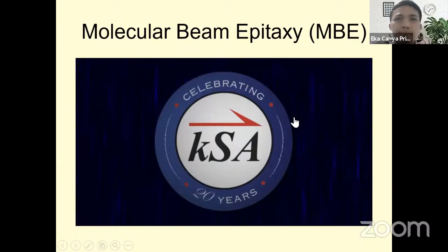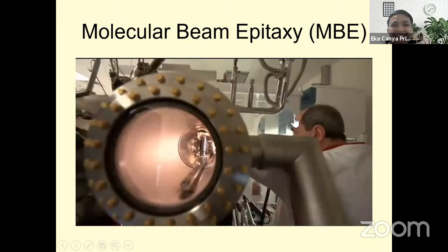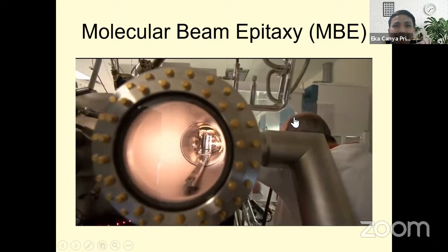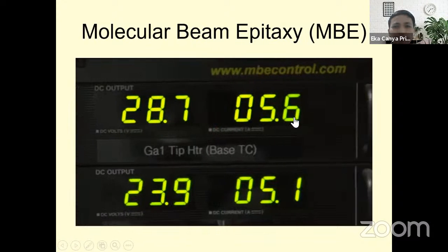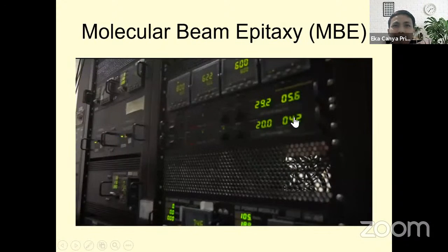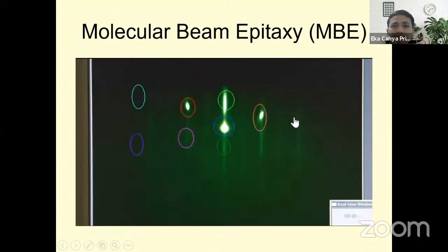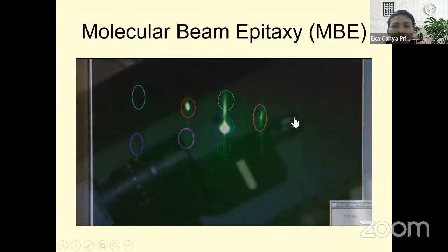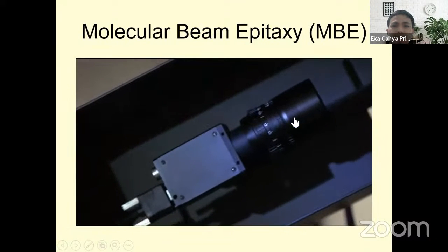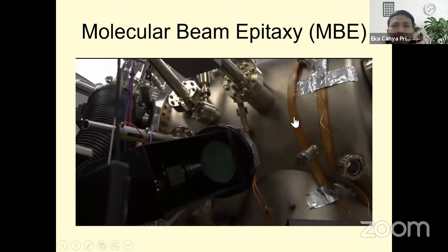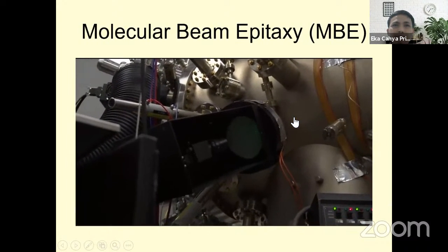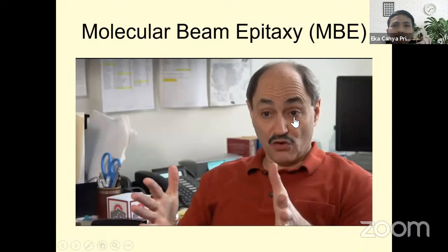It actually stands for Molecular Beam Epitaxy System. It's a big vacuum chamber with several thermal evaporation sources. The sources are all aimed at a center point where you put a substrate. We can change the electrical properties, the optical properties, the thermal properties. I sometimes explain it as a way of spray painting with atoms. And by engineering these stacks of layers that we're building up with the spray painting process, we actually make the first stage of a working either electronic or optoelectronic device.